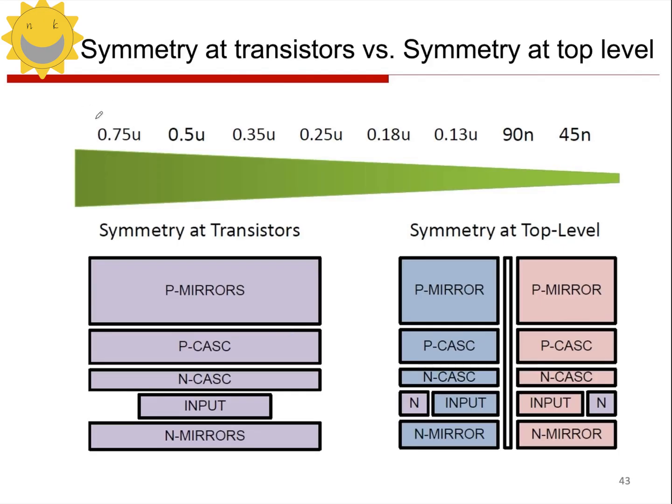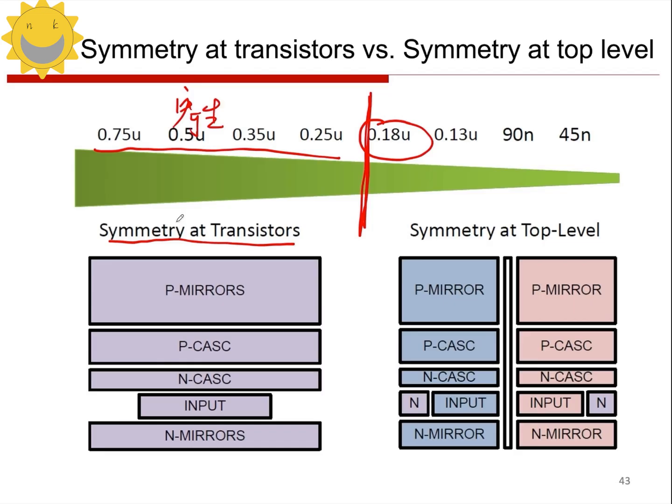So this is actually related to the process node. Let's take a look at the evolution from wide lines to fine lines, like the transition from 0.18 microns. You can see that 0.18 microns serves as a boundary, generally speaking, for process feature sizes above 0.18 microns. What do we generally prefer to use? Transistor level matching. So, generally speaking, for these coarser feature sizes, we use transistor level matching because the parasitic issues are relatively small at these process feature sizes.